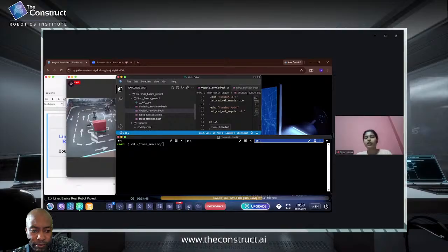I control the turning using the angular velocity and time. The angular velocity defines the rotation, and the sleep duration tells how long it rotates. By adjusting these two parameters, I can regulate the amount of turning. I set my angular velocity to -1.0 and sleep to 1.5.